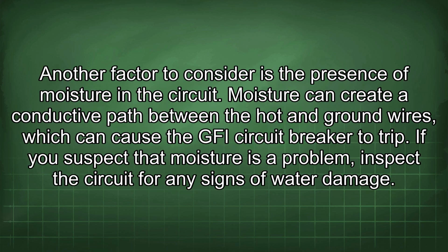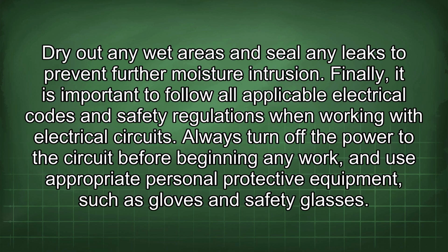Another factor to consider is the presence of moisture in the circuit. Moisture can create a conductive path between the hot and ground wires, which can cause the GFI circuit breaker to trip. If you suspect that moisture is a problem, inspect the circuit for any signs of water damage. Dry out any wet areas and seal any leaks to prevent further moisture intrusion.